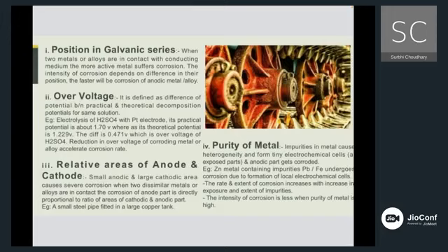There is also one other factor, that is stress. The portion of the metal which comes under stress acts as an anode. So metal oxide formation on that stressed area is more compared to the area of the metal which is not under stress. Thus, in the stressed area, exposure to the atmosphere and the corrosion rate are higher. If grain size is smaller, its solubility is more, hence greater will be its corrosion.